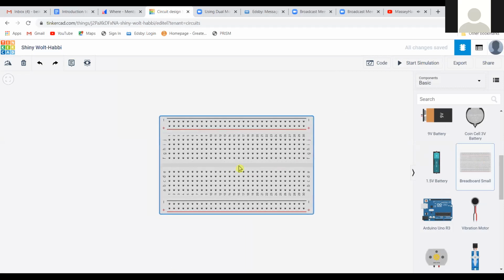For all of you that are new to computer technology, a breadboard is a way of building circuits that allows us to not solder all the components together. Underneath the plastic on the top is all copper. So when you stick a resistor through, it's got pins, and it connects to that copper and makes a connection.